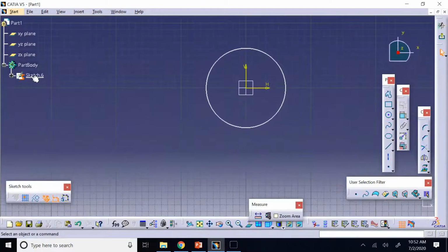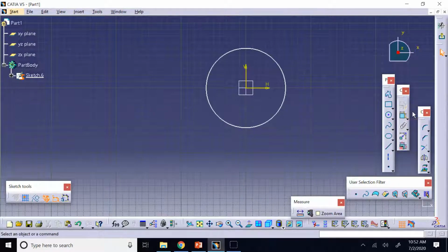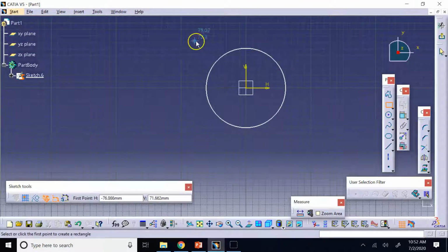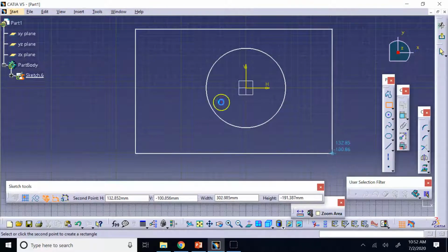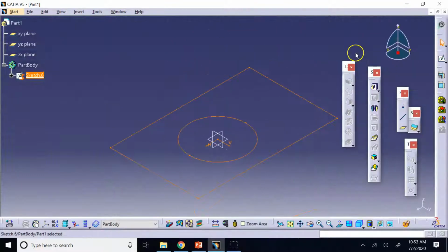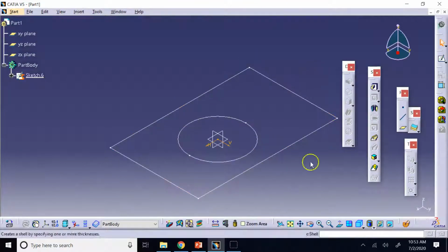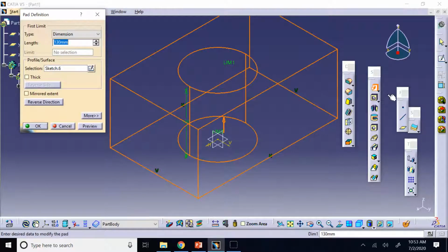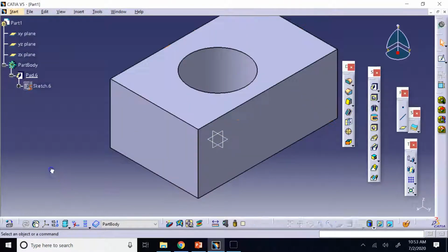If your original sketch has several basically closed profiles, so let's say something like this, right? You have now 2 profiles in the same sketch, 2 closed profiles in the same sketch. Can you pad this? So if I select this and say, hey, pad this for me, what does it do? It applies the pad to the whole thing, but that circle is considered as a whole, right? So you get this guy.